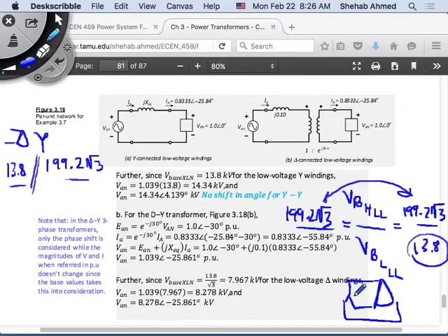As if you're going to take your delta now connected to a star, what is the phase voltage across the star connected load in that case? Exactly. It's 13.8 divided by square root of 3, lagging of course by 30 degrees. But here, for the base quantities, we don't care. Remember, bases don't consider angles. The base value does not change your angle. So the base value will be 13.8 divided by square root of 3.